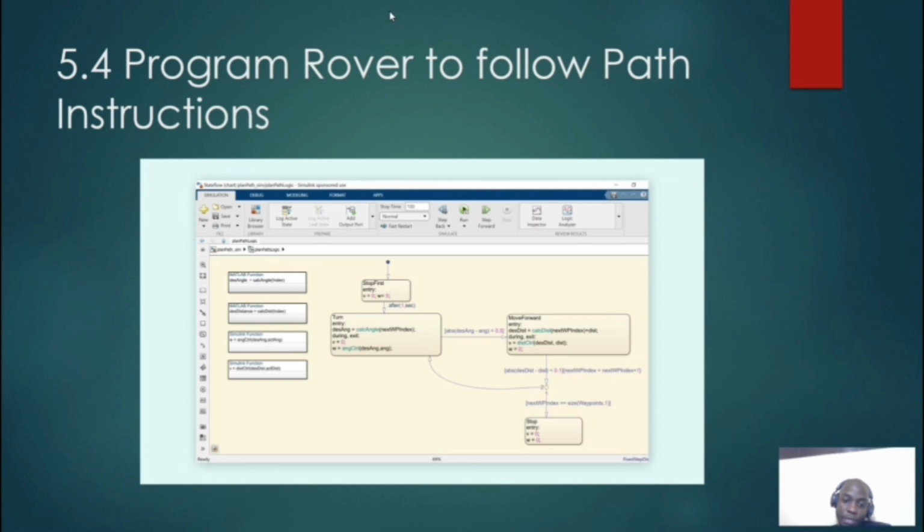The state-based approach is particularly effective at managing transitions and can inherently prevent overshoot by stopping the robot precisely when the conditions are met, rather than just letting a continuous controller potentially oscillate around the target. The state also calls the Simulink function that contains our PI controller algorithm to execute the necessary movement.